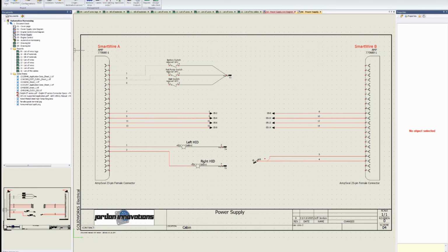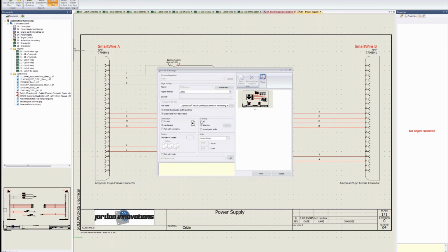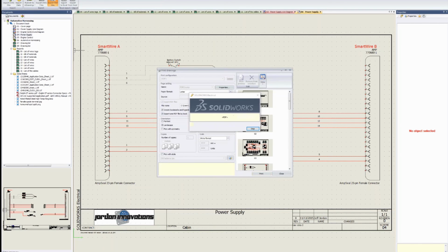it's incredibly easy to either, I can do a print if you're one of these people that still uses paper. I can go and export to PDF, right? So just right here, export to DWG, export to PDF, and my project will have everything that I need. One click, yes, go ahead and give me a PDF, takes 10 seconds, pulls everything in, and I'll show you what it spits out here.